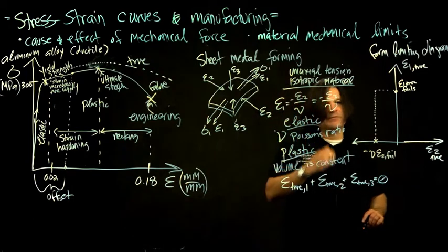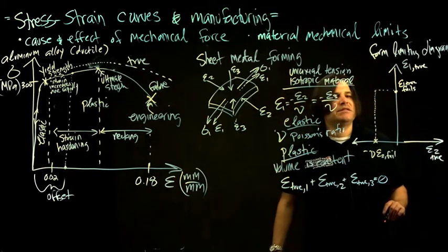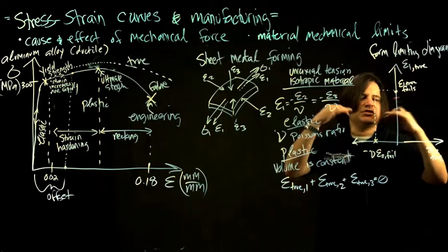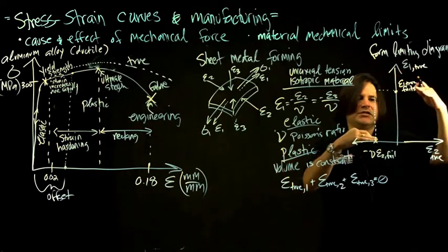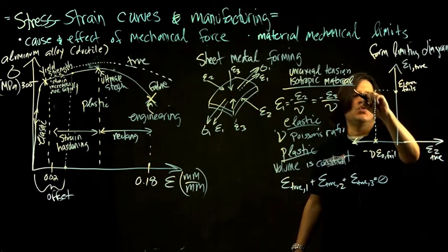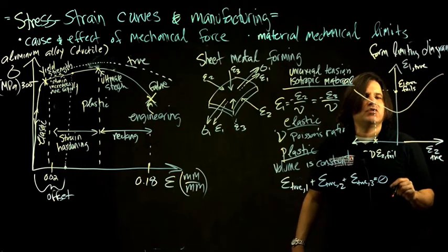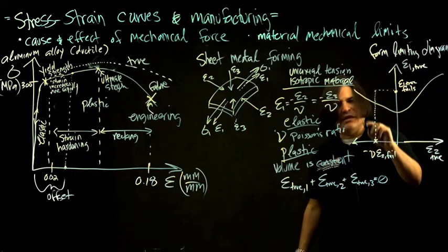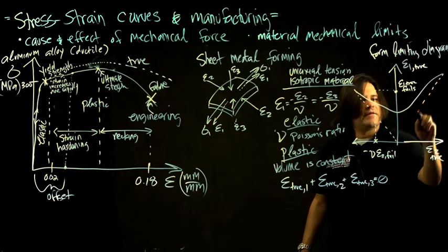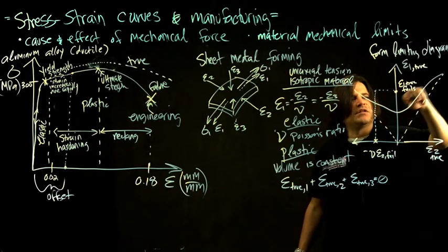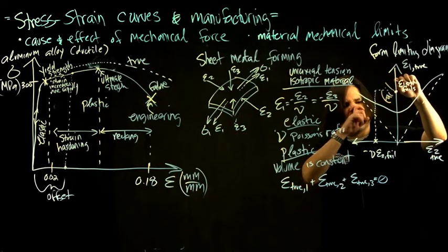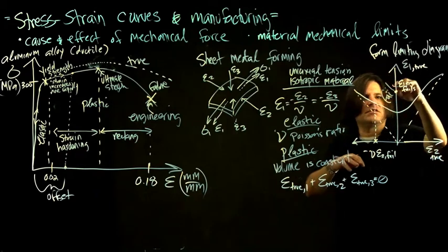So that's one benchmark. And then what happens is that you can do these tests like it's an experimental thing. You would have to look at the response of a strain in one dimension and a strain in the other dimension to see what happens. And what gets mapped out is this locus of values where something like this, it forms kind of like this boomerang triangle thing, where anything above this line is a failure, meaning the material will not survive this amount of stresses due to deformation. So this is the failure regime.